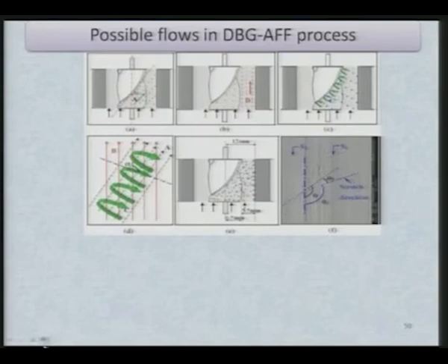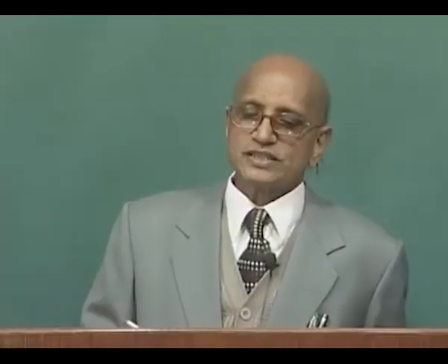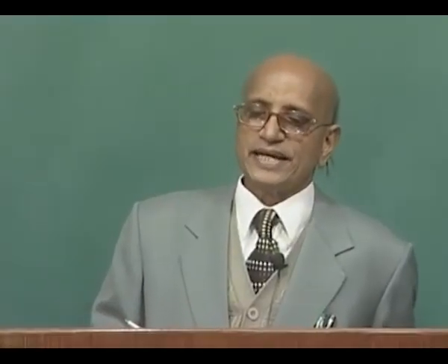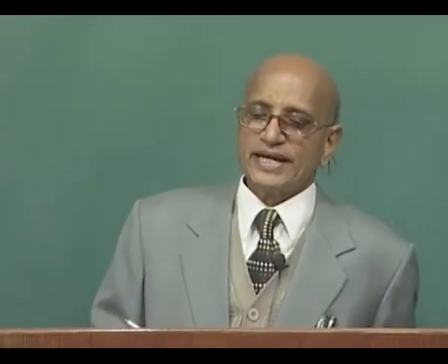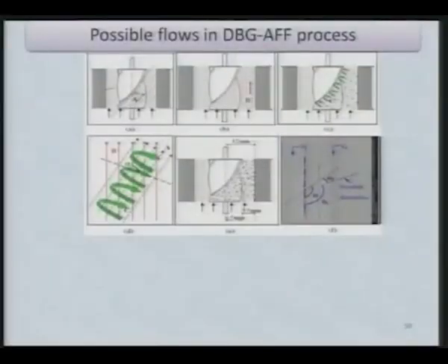Then there was drill bit guided abrasive flow finishing in place of the screw. Some of the researchers have used the drill bit, and they rotated the drill bit, and the same logic holds true here also: the space available for the flow of the medium decreased, and because of the decreased area or volume of this space, the radial force that acts on the abrasive particles and gets transferred to the workpiece surface is higher than the case when there is no such drill bit.